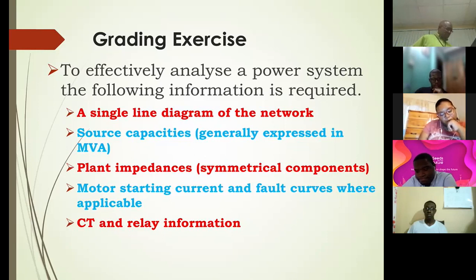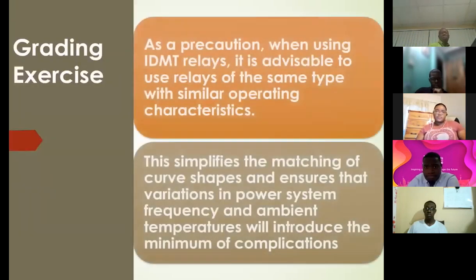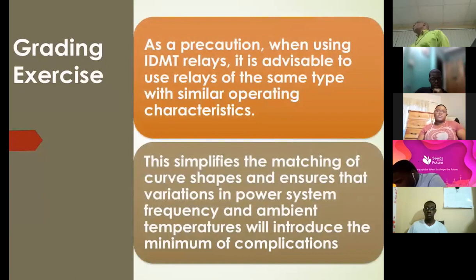And just a note: when you're using these relays, you want to use relays having the same characteristics. So you're not going to mix IDMT and not IDMT, very inverse and extremely inverse. It's not that it cannot be used.